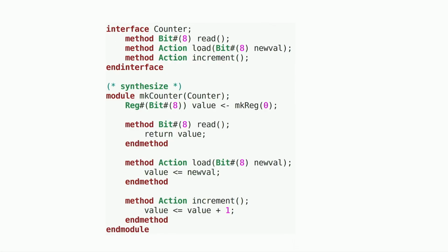And what's different from SystemVerilog is that you can have different bits of code which operate on a shared state, write them in different places, focus on just what that bit of code does, and then Bluespec will stitch things together itself and schedule them in some way that's totally safe, that avoids race conditions, etc. If you had to write that in SystemVerilog, you are the scheduler. You have to write all that code, and it all gets written in one place, in one block, with no modularity. So that's already a huge advantage.